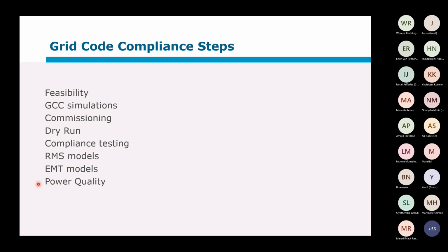So the distributor has to now review the power quality compliance and advise RETEC that they accept it, if it is obviously compliant. If it's not, that also goes back to RETEC, and the generator is informed that there is a non-compliance, which they have to fix.